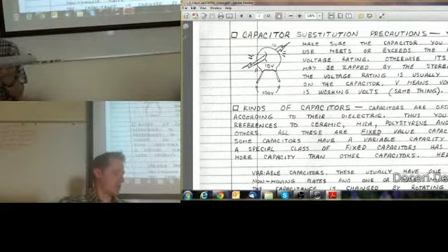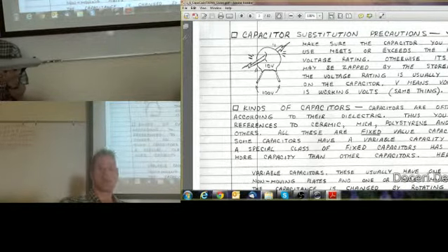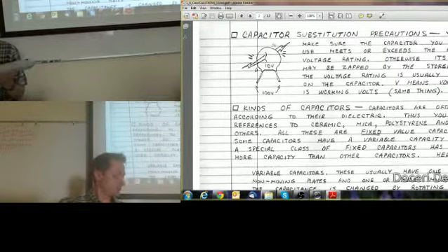And you also notice that the electrolytic capacitors are polarized, which means you cannot reverse the voltage across those. But ceramic capacitors and all other capacitors, you can. They're non-polarized. The only ones that are polarized are going to be electrolytics and tantalum capacitors. And we'll discuss that when we do a lab.